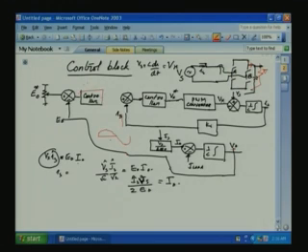Okay. Then we will generate a sinusoidal signal, which is in phase with our Vs, that is sin omega t. We have to generate a sin omega t with unit amplitude. This we should multiply with these two.